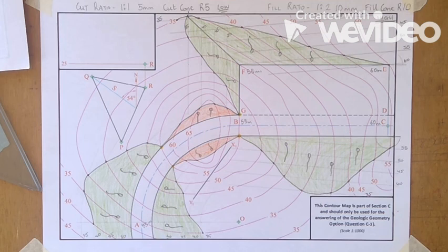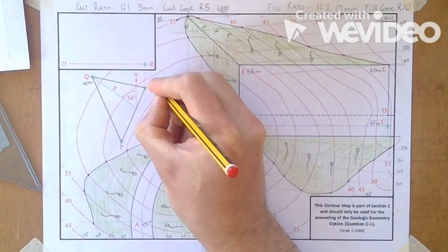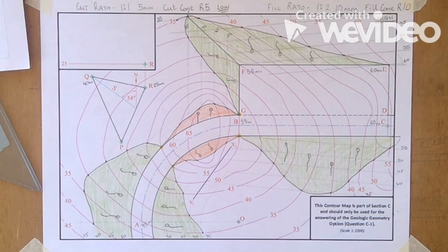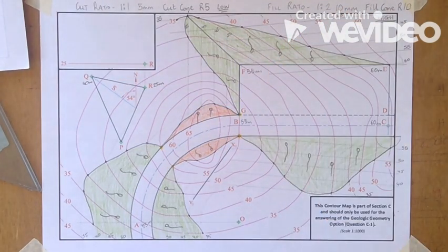So it says on the map, P, Q and R are 3 points on the top surface of the stratum of ore. Q and R are the altitudes at 40 meters and 25 meters respectively. So Q is 40 and then R is 25. The stratum has a strike of north 54 degrees west as indicated by the strike line. Okay, so there's your strike. Using the X1, Y1 line already drawn on the map, determine the dip of the strike.